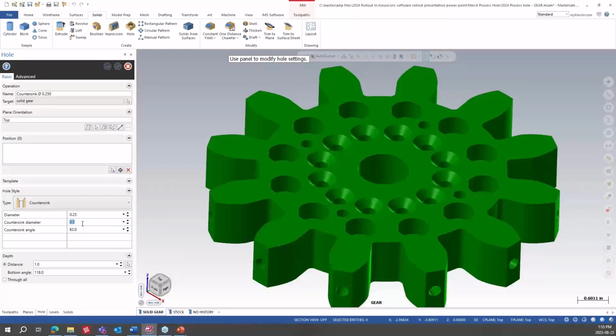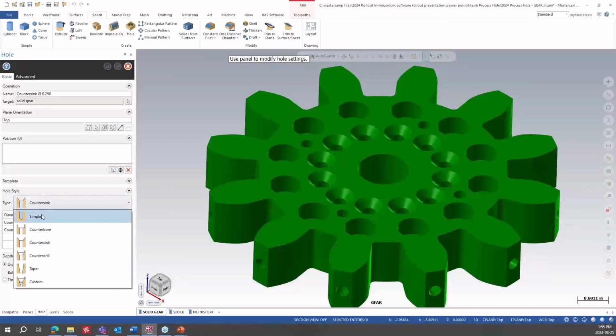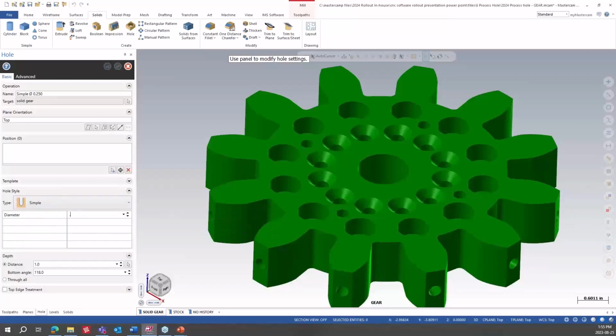And if you set your process hole up, so for this one here, we could set this up, change that to 234 hole or 235 and go from there. Now, when you pick that on the solid, it'll find that in the process hole tool library, and you'll be able to pick that operation. Associated correctly. Yeah. Okay.